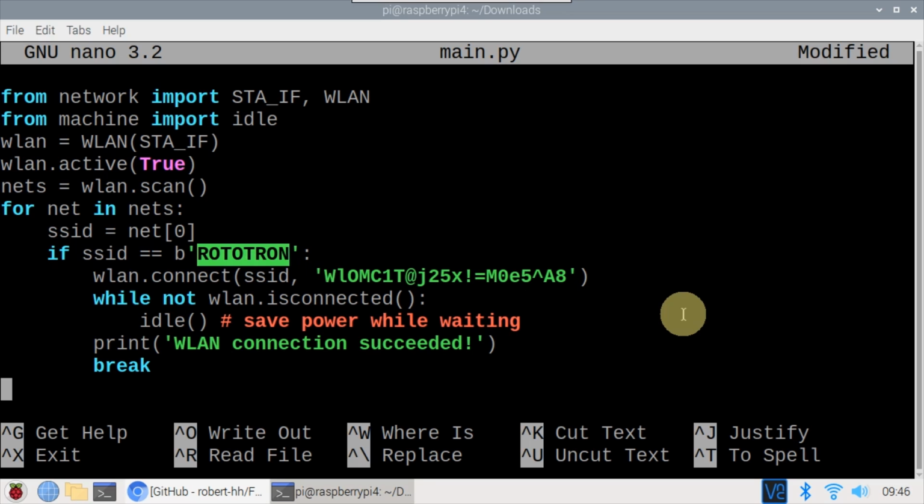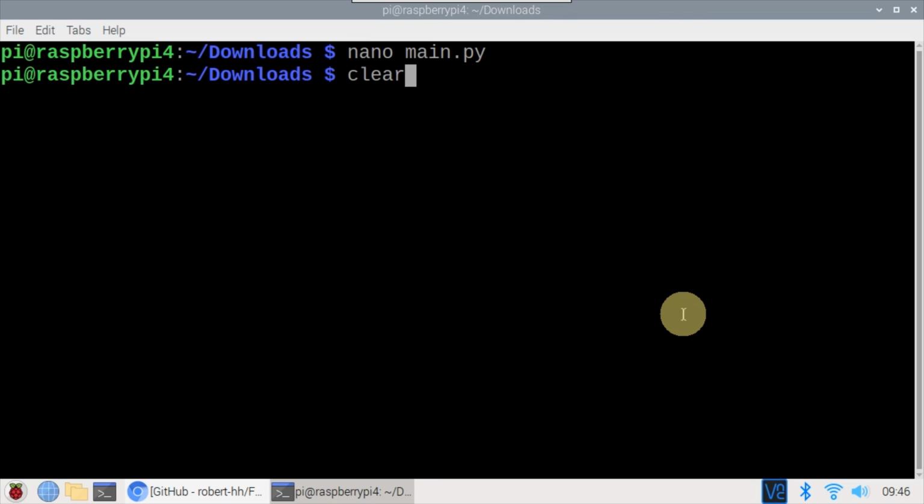I've already covered the main.py file and FTP access in my previous ESP32 tutorials, and I've demonstrated how to set up the ESP32 and necessary tools such as esptool to load the firmware and rshell for REPL and file management. If none of that sounds familiar, I recommend you watch my prior videos too. Ctrl-O saves the file, and Ctrl-X exits nano.